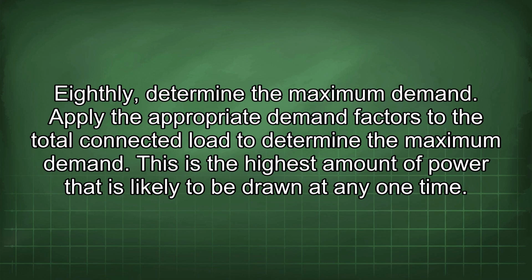Eighthly, determine the maximum demand. Apply the appropriate demand factors to the total connected load to determine the maximum demand. This is the highest amount of power that is likely to be drawn at any one time.